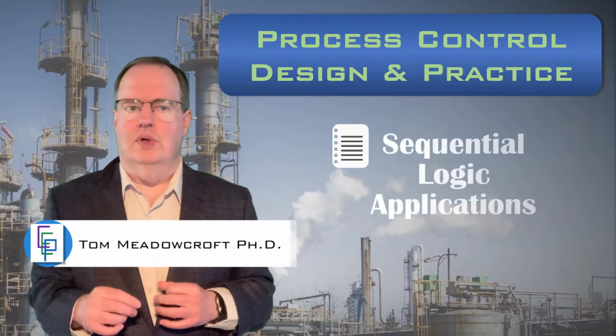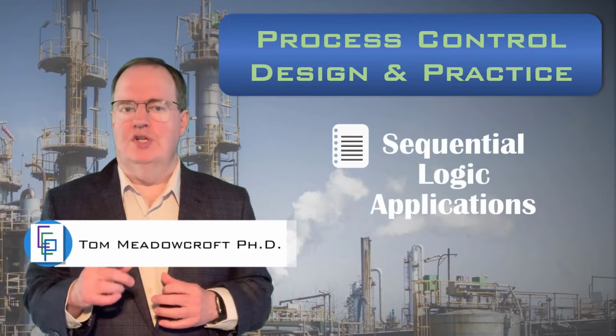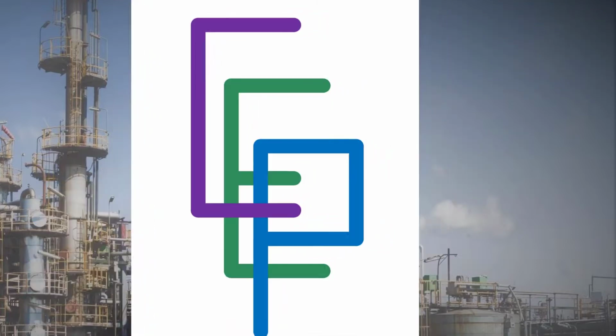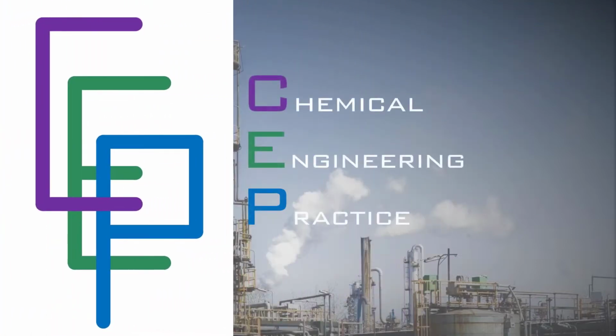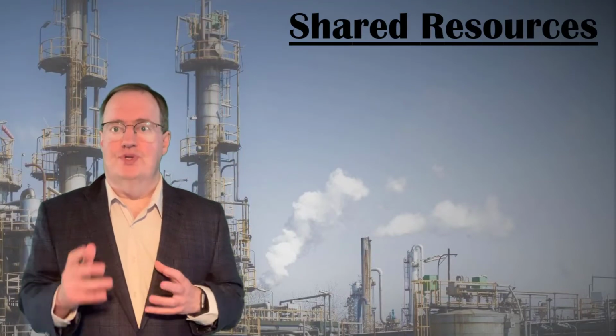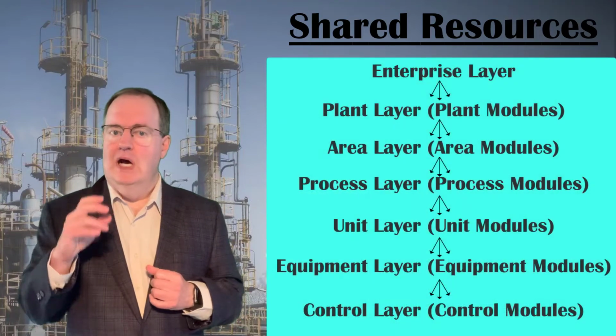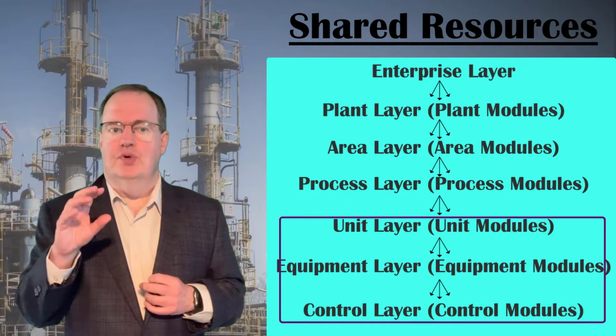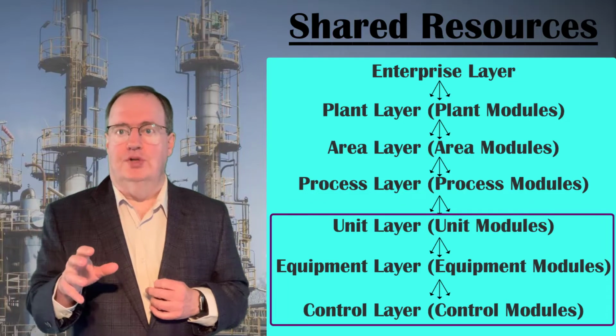In this video, we will learn about applications of sequential logic outside of recipes and phases. The first topic we will visit is shared resources. We talked about how in the S88 hierarchy, we would focus on unit modules, equipment modules, and control modules.